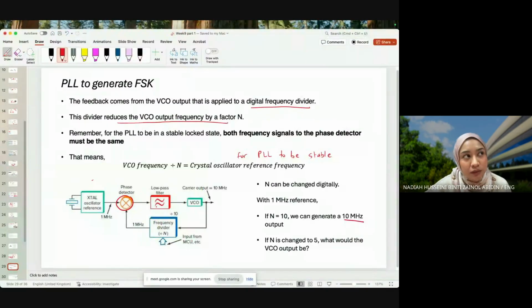And when it is 90 degrees, it's going to produce 0 volts. And if it is 0 volts, it's going to tune at the natural frequency of the VCO, whatever I tune it to be. The natural frequency in this case is going to be 10. And if I change N, I can change the entire thing. N is going to control everything. So basically, you need to understand how N works to change the frequency. It's just this equation.